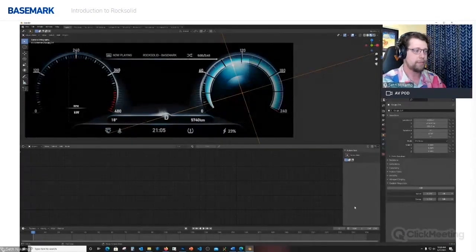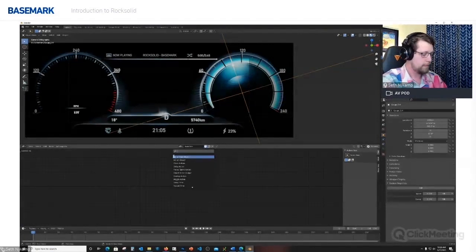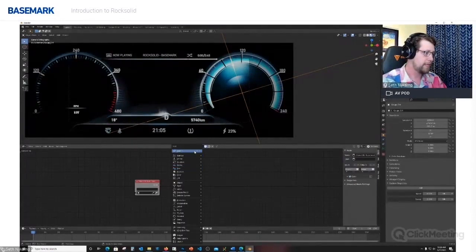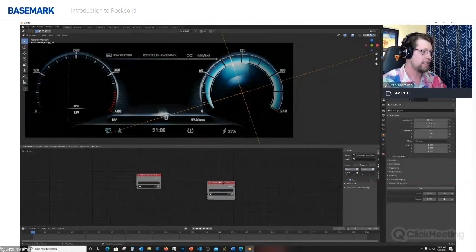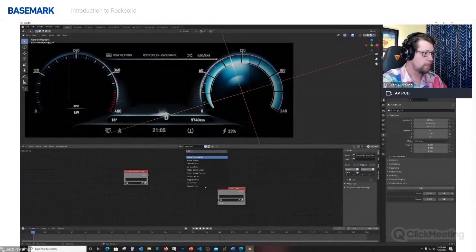So now it goes from 0 to 240, and now I want to map this 0 to 240 custom property to control all the other elements. So the rotation and everything should be controlled through the speed parameter. So let's go ahead and set that up. I'm going to add in some attribute inputs and some attribute outputs. And what I'm working in now is called animation nodes, and this is a visual scripting program. So this allows me to set up logic and cache that data.